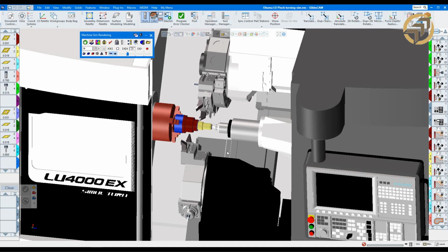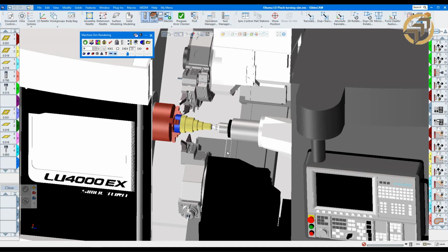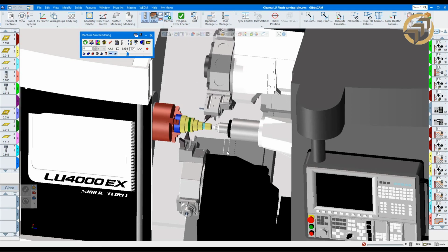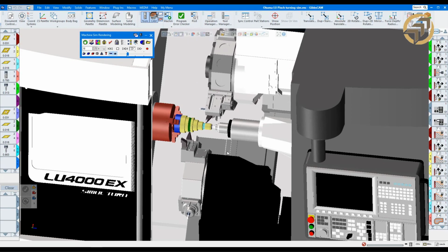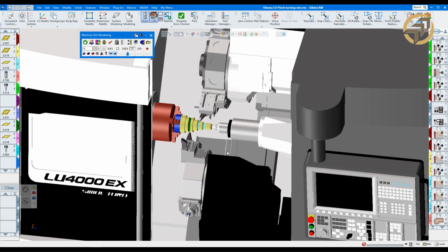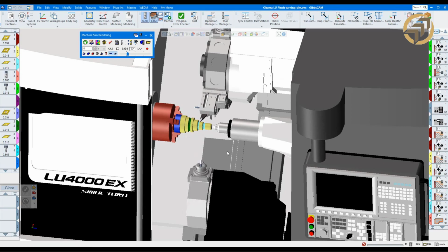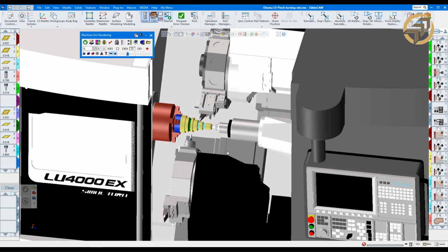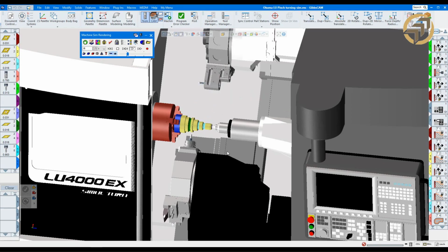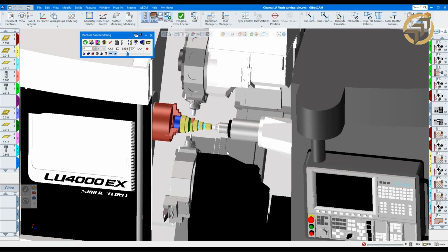Simultaneously, then the upper turret comes and is doing some finishing on the OD, then the lower turret also joins in, grooving some kind of a V-groove. The upper turret is doing some thread reliefs, things like that. Basically machining the part simultaneously, and this is what MTM is being used for, how to program these type of machines in GibbsCAM MTM. And since we're talking about it, MTM stands for multitask machining, which we're doing right here with that machine.